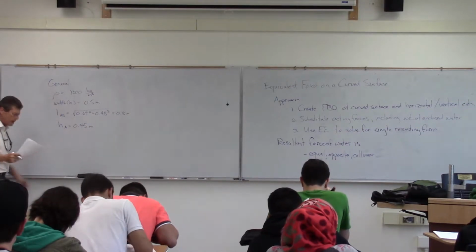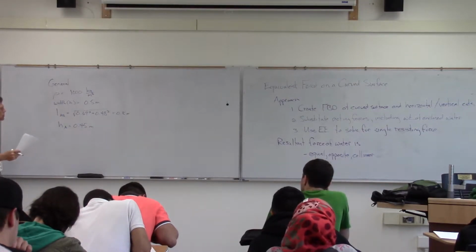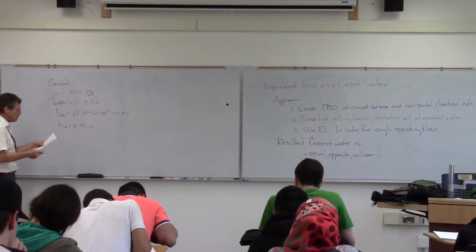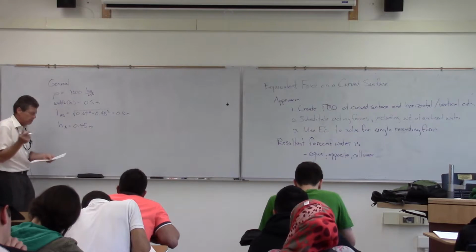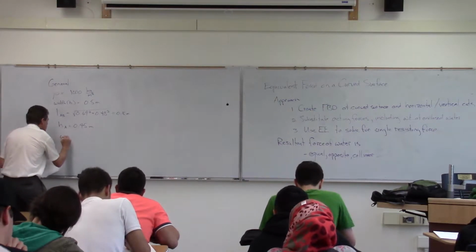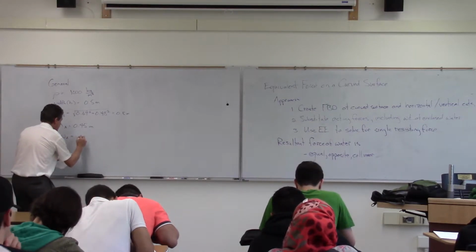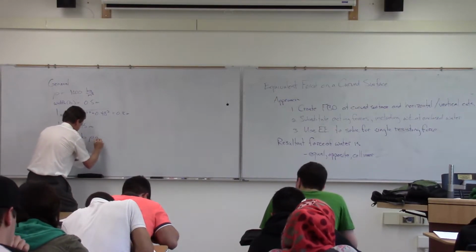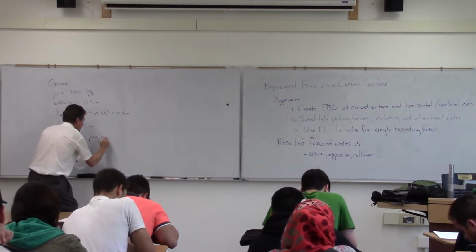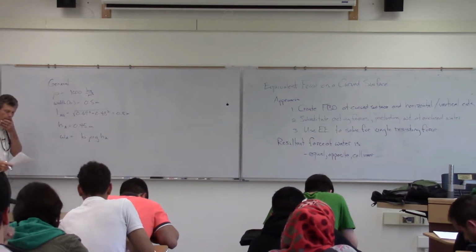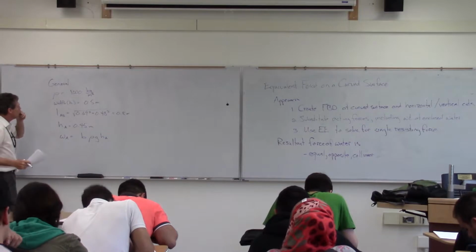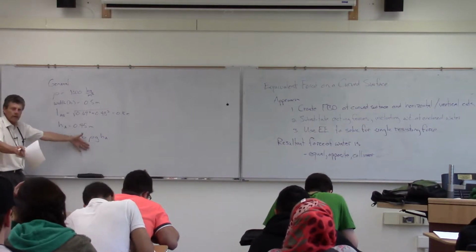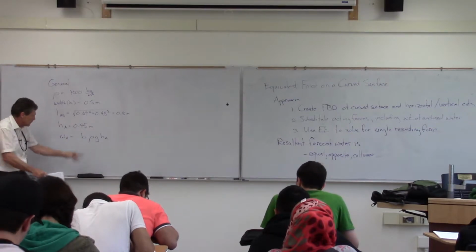Okay, so my depth to my first point of interest at A is going to be 0.45 meters down. What I'm going to do is calculate what the equivalent beam load would be there. So my WA would be this. Now the one tricky thing to note here, B is my width, so I'm getting rid of that and bringing it down to a linear load.